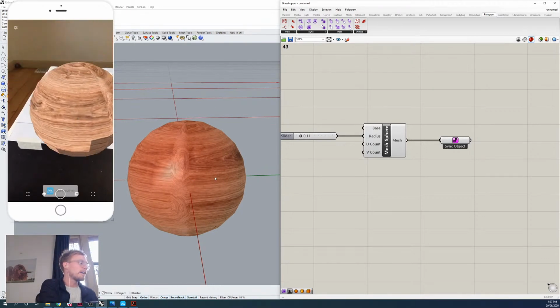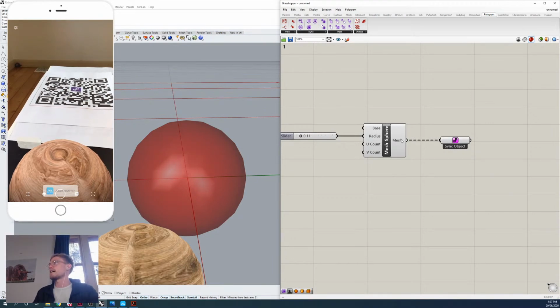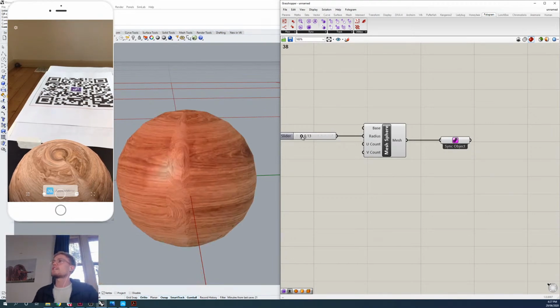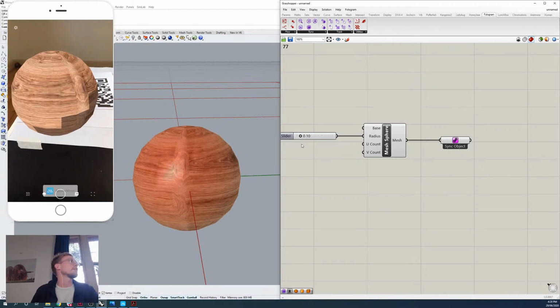So just be aware of that little dashed line there. If you see that and you change a parameter previously, you'll lose the transformation data that you've got there. So everyone just test out that little relationship if you've got some issues there.